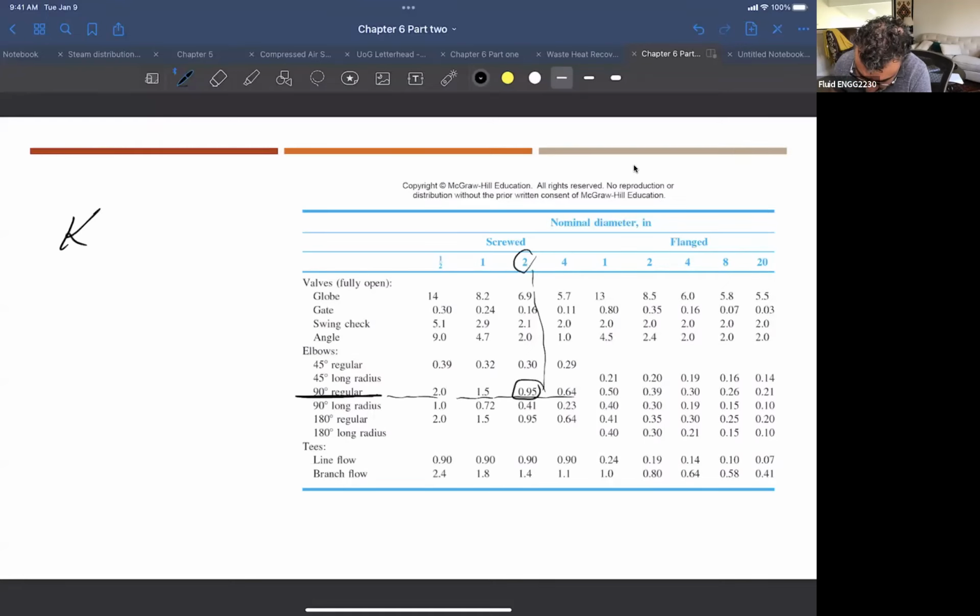So the K of bend 2 is 0.95, okay? It's going to be a systematic approach of solving this type of problem, and most design problems are like that, right? So you will find all the components, find all the K for these components, and make sure you use the summation of these K if you are connecting this piping in series, right?